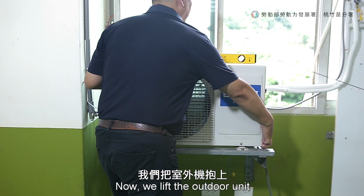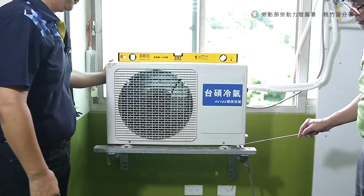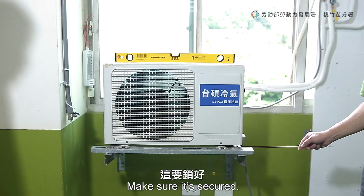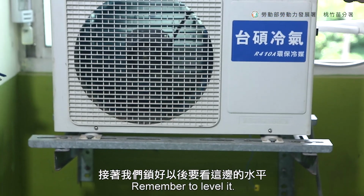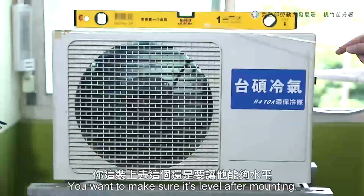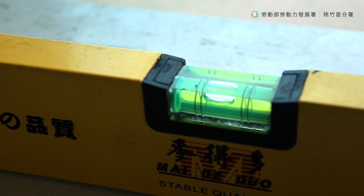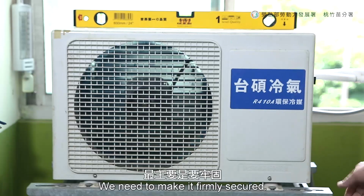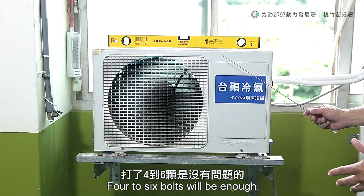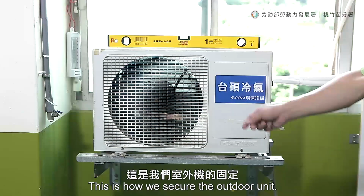Now we lift the outdoor unit onto the mounting bracket. Secure this part of the bracket. Make sure it's secured. Remember to level it. Being level isn't enough. You want to make sure it's level after mounting. We need to make it firmly secured. We used expansion bolts just now. 4 to 6 bolts will be enough. This is how we secure the outdoor unit.